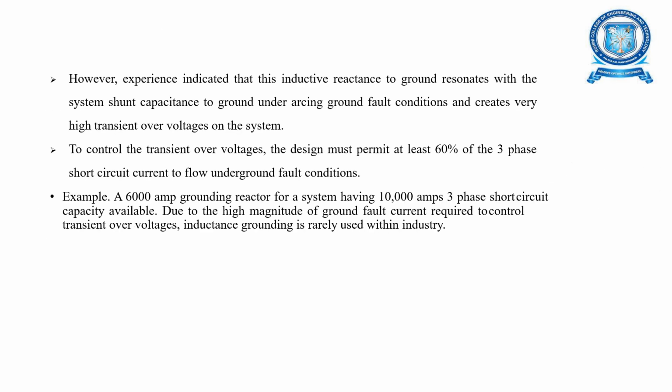However, experience indicated that inductive reactance to ground resonates with the system shunt capacitance to ground under an arcing ground fault, and creates very high transient overvoltages on the system.